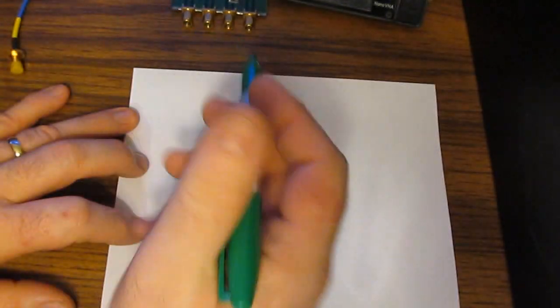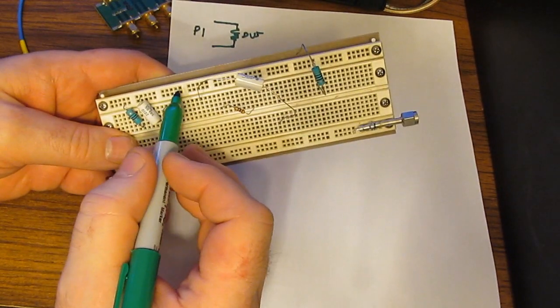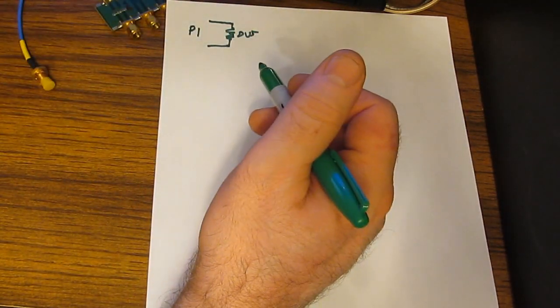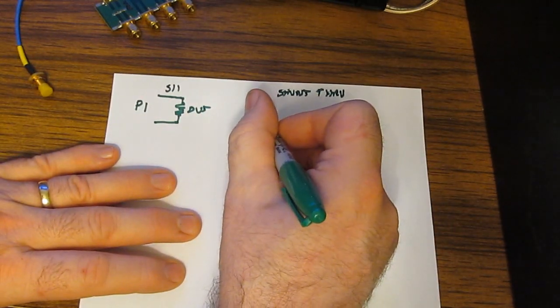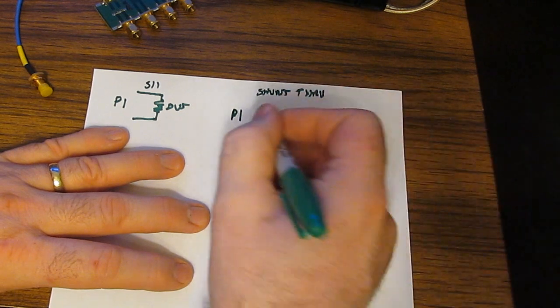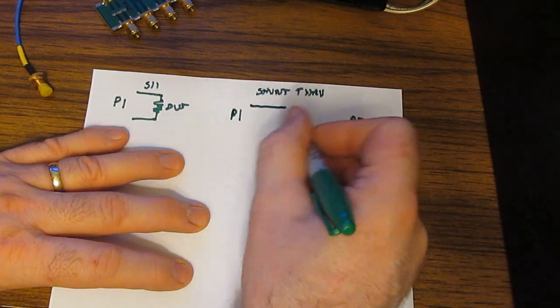So let me just talk a little bit about what the shunt through measurement is and why we would want to use it to measure the PDN. Why can't we just attach port 1 directly to the power plane of our device and measure the impedance that way? If we look at the shunt through method, we're now going to use port 1 as well as port 2, and we're going to place our device between these two.